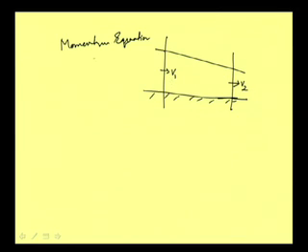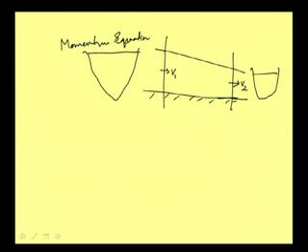So, the sectional area at this one is this, and here suppose it is this one, and suppose the discharge flowing is Q here, and the discharge flowing through this part is not changing, so it is also Q. Now, we know what continuity is. So, in this section Q is flowing here and Q is flowing there also. So, what will be the mass? Mass will be equal to rho into Q, density into Q.